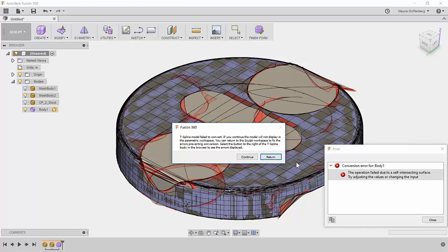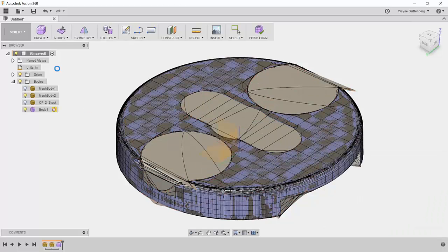We had a question about Inventor, and does Inventor support mesh data? And the answer is yes. The products are at slightly different development schedules, so one might be catching up with the other at certain times, but yeah, these workflows work in Inventor. I'll add that SolidWorks has no support for mesh data, but our HSM Works product is capable of machining on a mesh. The truth is SolidWorks just doesn't know it's there. We kind of float it in the background and let us toolpath the mesh. So I think that's worth mentioning.